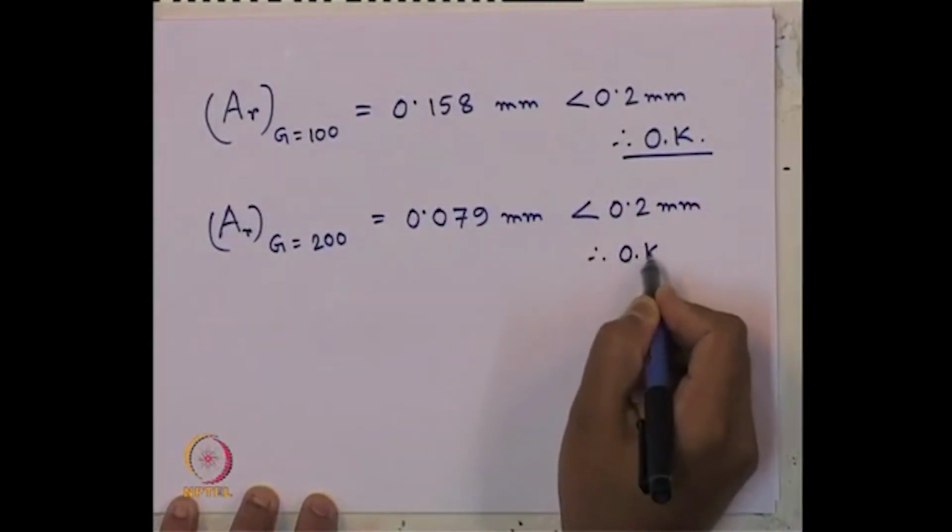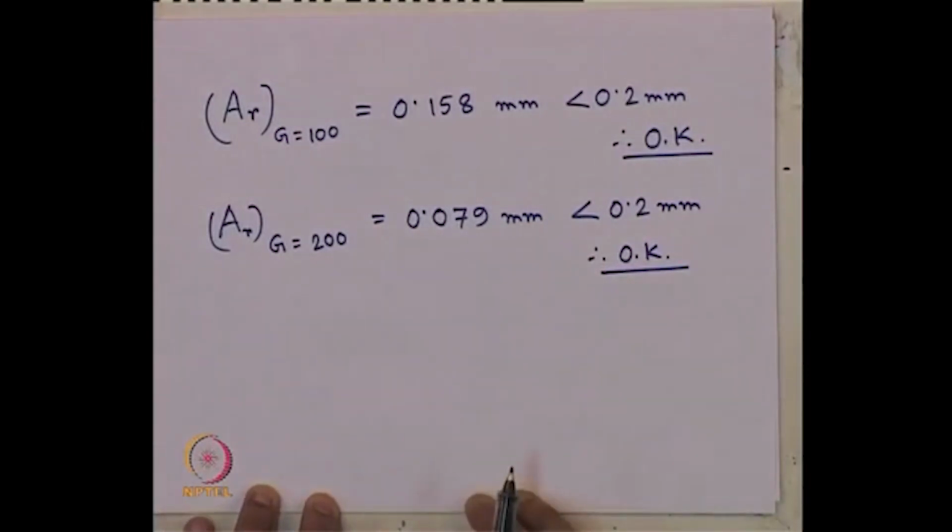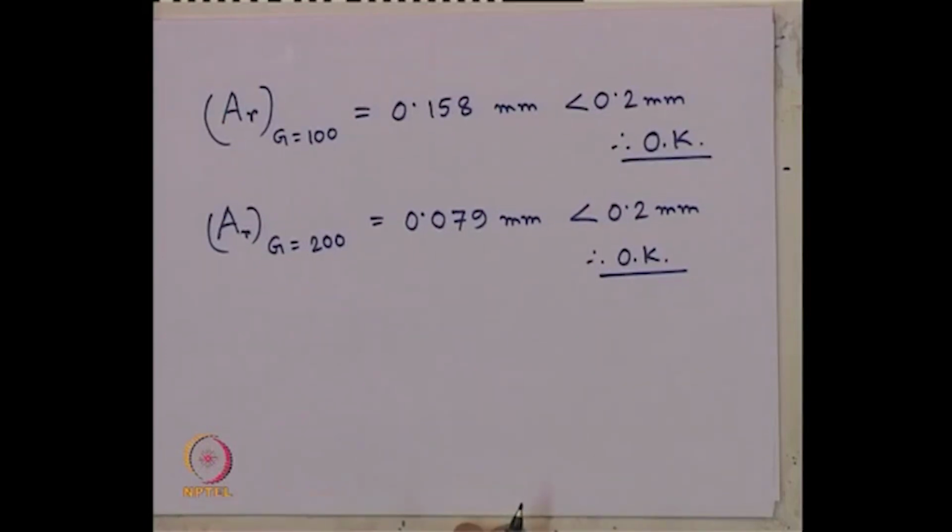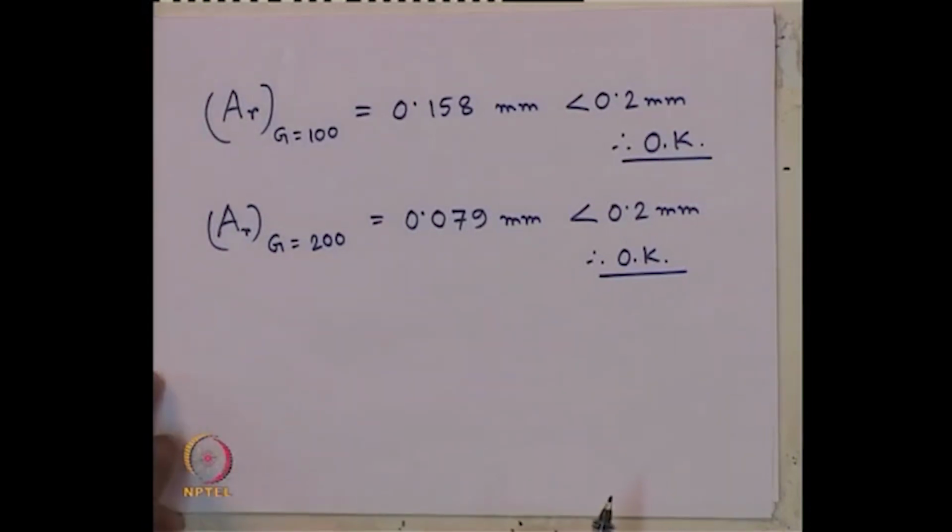Therefore, here also design is okay. So, for second and third type of soil, the design is perfectly all right, whereas for first type of soil caution will be it should never be close to its resonance condition. So, these are the discussions or comments we need to make after doing this design check. So, this is for constant force type excitation.